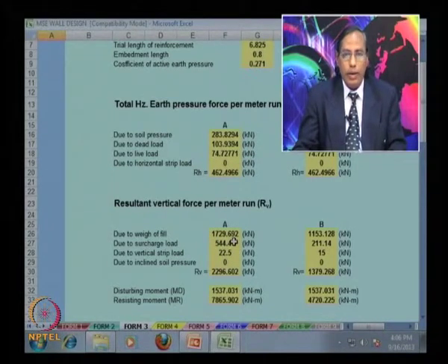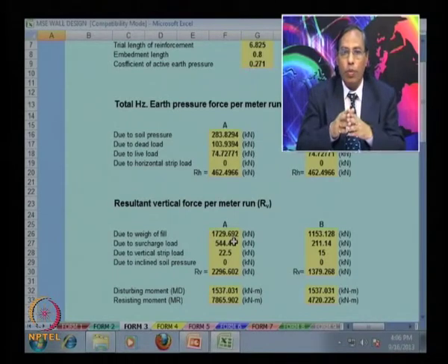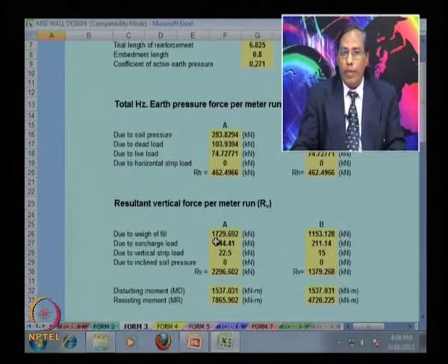You know that a reinforced soil wall has a height capital H, L is equal to the length of the reinforcement, and gamma is equal to the unit weight of the reinforced soil. So weight will be equal to gamma into H into L. You know the gamma for the reinforced soil zone, the height of the wall is given, and you know the length of the reinforcement.